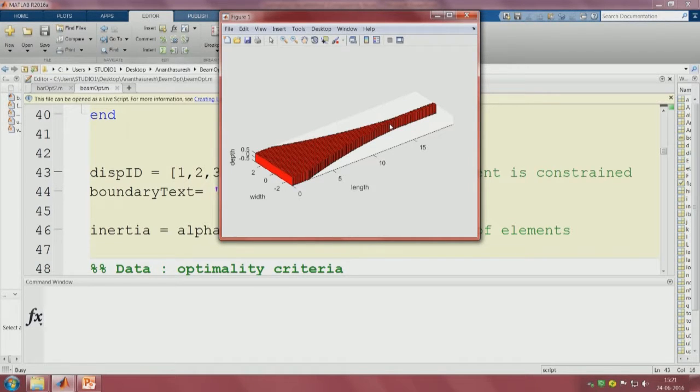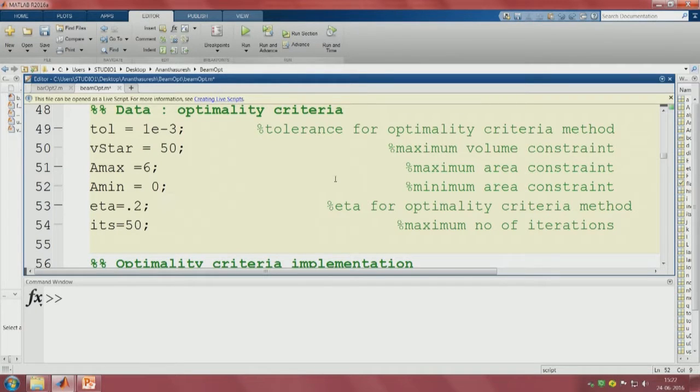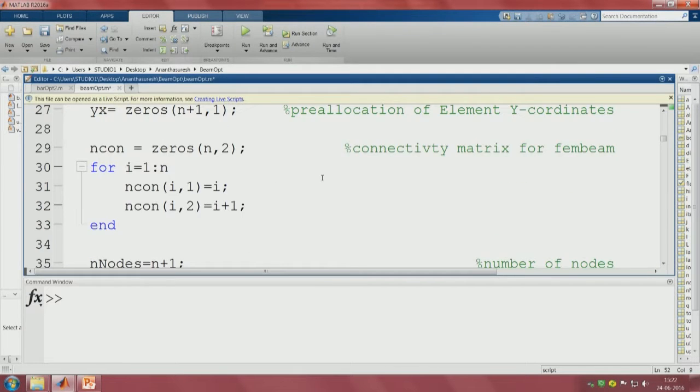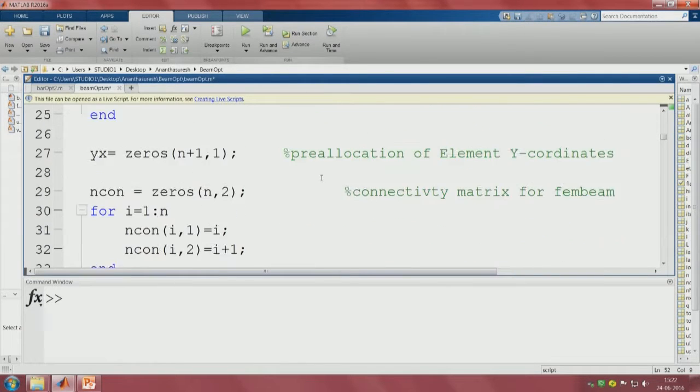Okay. So, you should learn by trying it several times. By looking at it, you should be able to guess the boundary condition, it is fixed and free. Okay. We can try lots of different boundary conditions, fixed and guided and many others. Okay. Fixed and guided means that we fix it. Okay. Let me bring back, so, Control Z. So, that will make it 1. Okay. So, going to this displacement boundary conditions, where did it go?